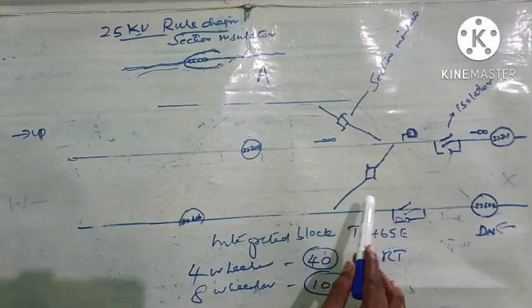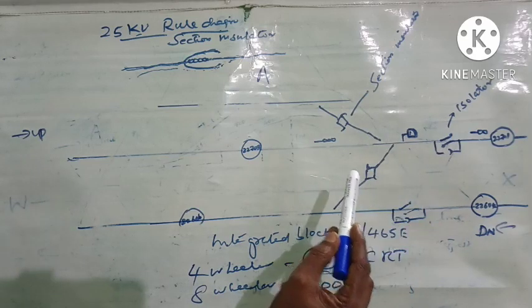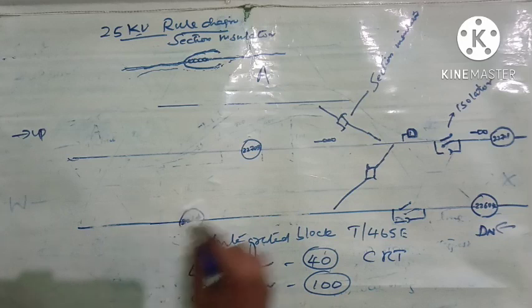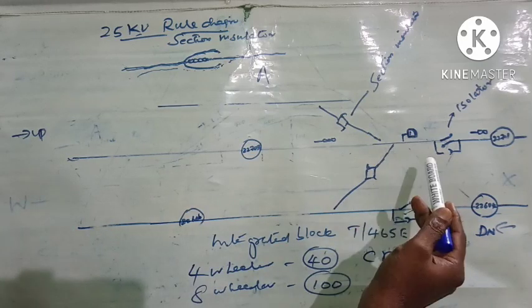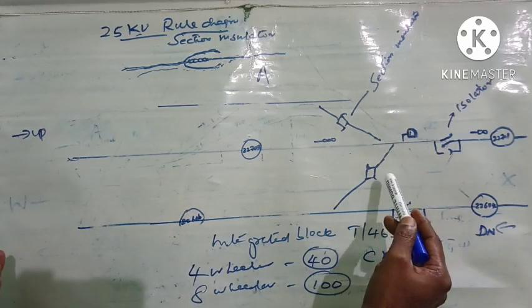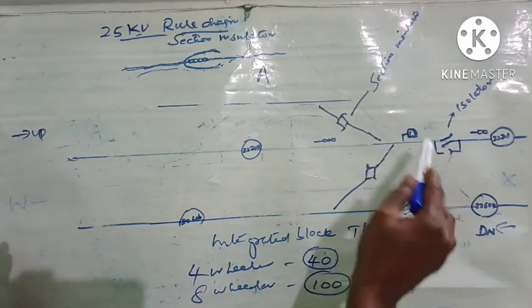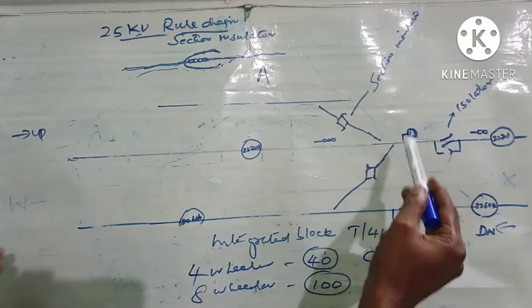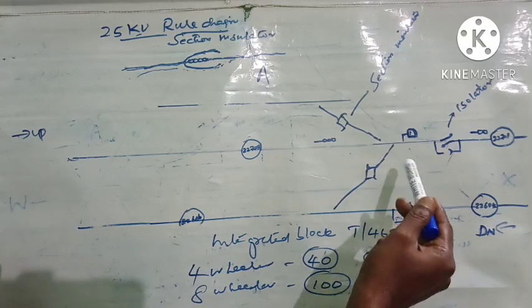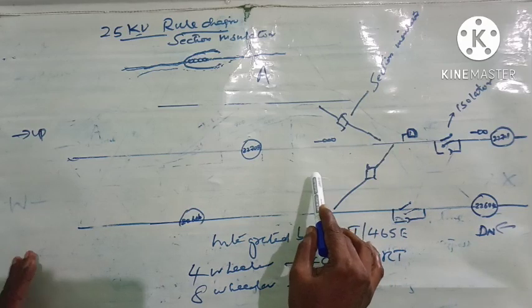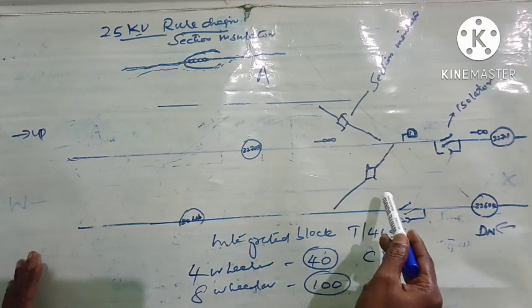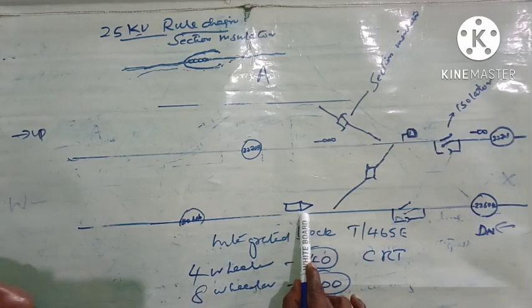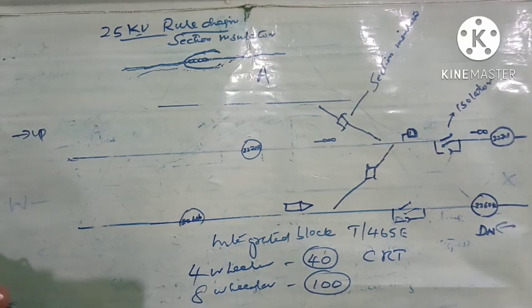And the TPC has control over this OHE line, and by sitting in a remote place he can switch off the line. Switching off the line means the electric loco naturally will not get power and it will come to a stop. So in order to stop trains in such emergencies, the message can be given to the TPC under exchange of PN. Now let us see whether shunting can be done by an electric loco towards a line where power block has been given.